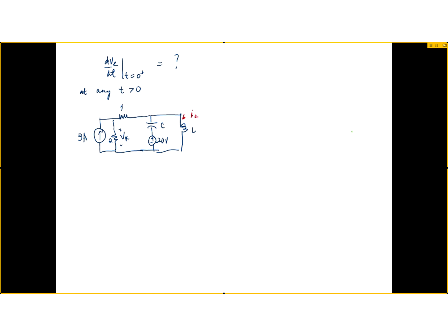IL, right? Because I already have dIL/dt, right? And what's the other variable? VC. Right? So somehow I need to find an equation that involves this VR and relates it to either VC or IL. And even both of them is fine, right? Because both of those derivatives I already know. So how would I do that? Well, you can use any circuit principle that you want.